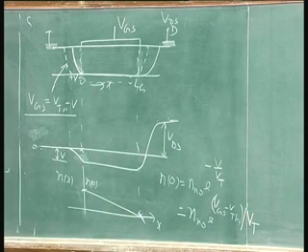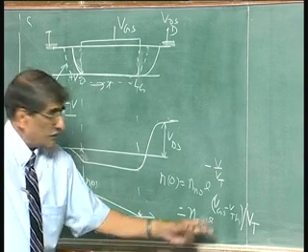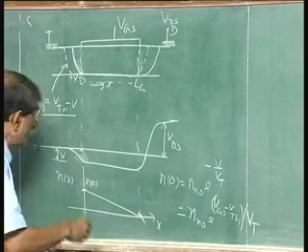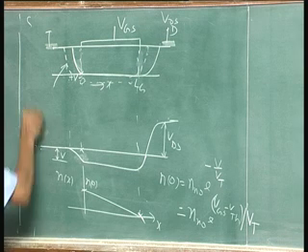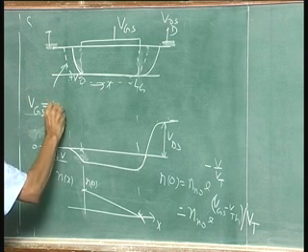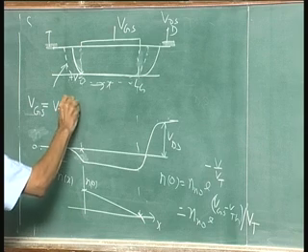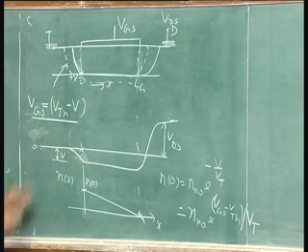So, you have got this particular term now. I hope this is clear, that we have obtained it from here, because we started off with that. Recall here, let me put it once again here: VGS is, we are seeing, just below the threshold voltage by an amount equal to V. So, V is equal to VGS minus VT threshold.